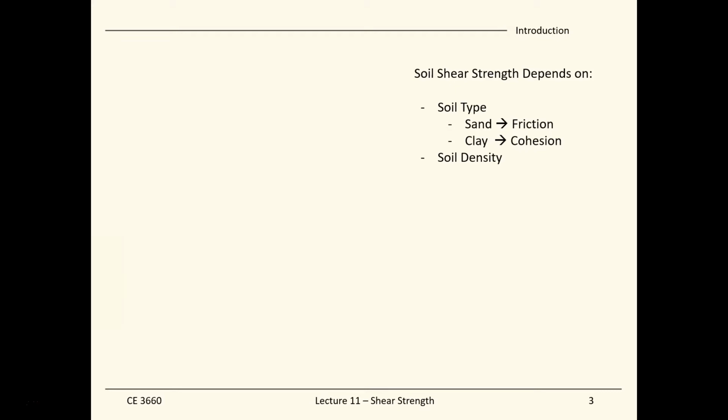Also, soil density matters, and the stress history matters. We learned about this in the third semester. We also talked about this in the topic of soil consolidation, where the maximum past pressure is characterized, which means we can find out the effect of stress history on soil strength, which is also an important factor. Also, the geological setting of the site plays an important role when it comes to soil strength. Last but not least, the loading mechanisms also matter.